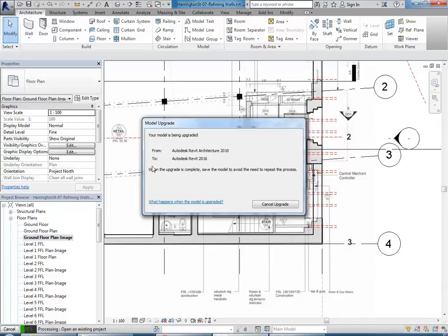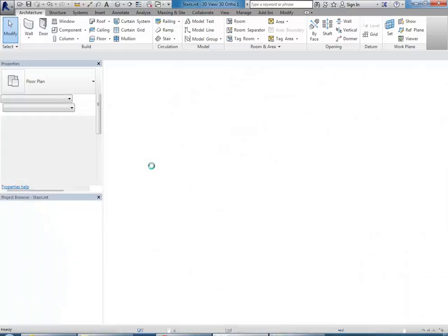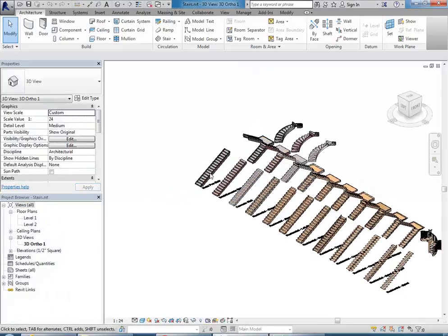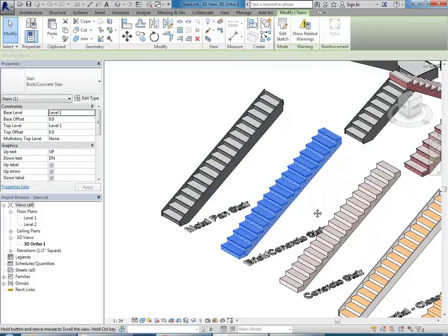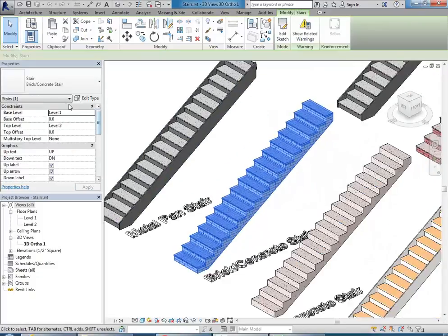So that can get you out of trouble, because if you've made it with, say, sketch-based stairs, often you just want to change the construction to another kind of stair, but you can't do that if it's assembled or assembly-based. And you can tell when you select them in properties, it'll say stair and then the type.